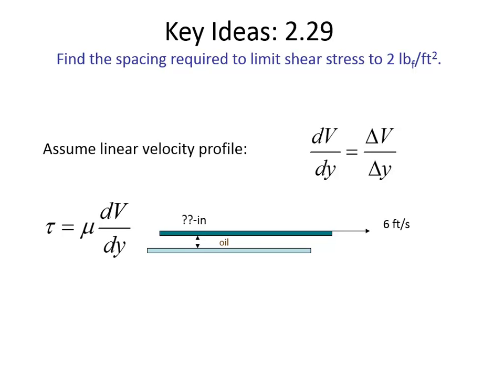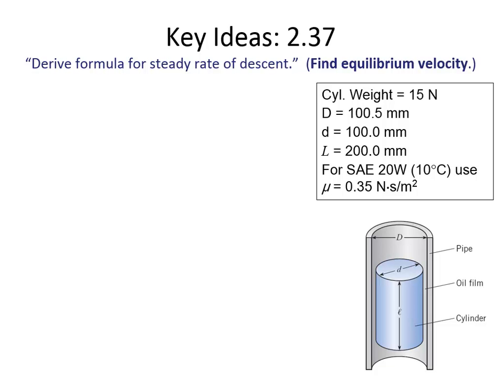How do you convert from shear stress to shear force? It's the area. Yeah, and the good hint is the units here. To get them equal, you have to multiply by the area. And so in this falling cylinder problem, there's an area that is experiencing this shear stress, the shear stress of the oil resisting its movement.